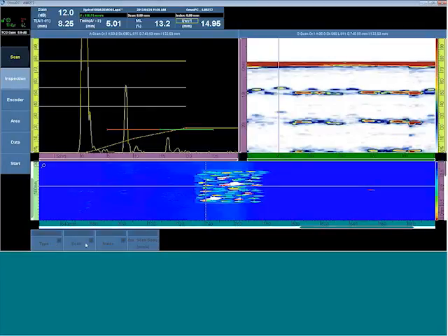So if we look at the scan menu, in this inspection, we've selected raster scan, and now we have to assign encoder 1 and 2 to the scan and index axes. So instead of just having one encoder, now we would have two, and they would both be configured independently with a resolution and an origin position. In a one-line scan, we only saw available the configuration for the scan axes start, end, and resolution.